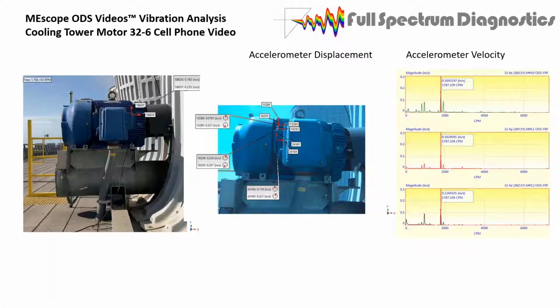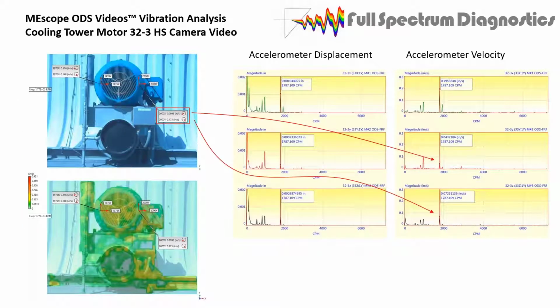Next. Can you see looseness between motor and base using phase derived from your image? Oh yeah, sure. That's one of the best things for it. All the problems that develop in vibration analysis that are phase related are unbalance, eccentricity, misalignment, looseness, bent shaft, cocked bearings. Mechanical looseness type A is a loose bolt or a broken flange or what have you, a cracked weld, and you can see relative motion.